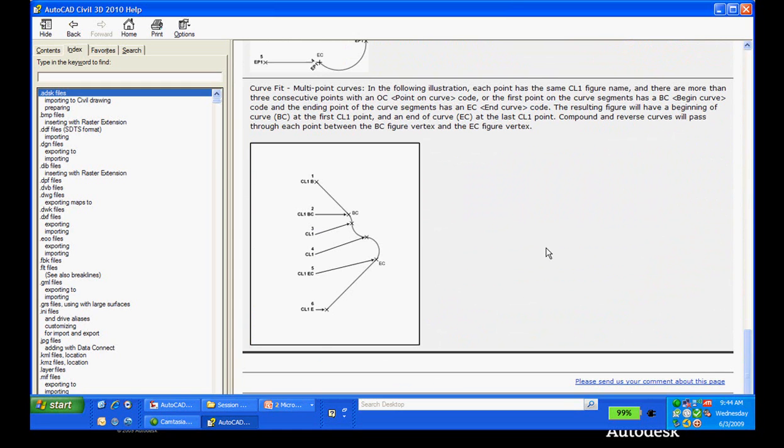All right, linework. If you're picking up stuff on a house, I can't always see all the interior points around the building. Maybe I'll see just some of the outside. Well, there's codes that I can take a shot and then maybe take the next shot to establish the line, and then I can say I want to go right so many feet. They don't have right and left. It's right positive, it goes to the right, or right negative, and it goes to the left. But we can add values and march our way all the way around the building in that as well.